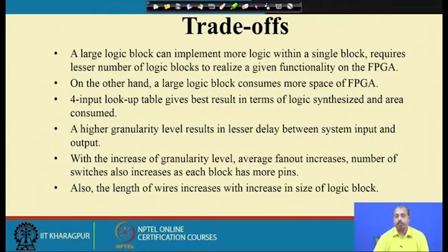On the other hand, a large logic block consumes more space on FPGA. As I said, for example, take this Xilinx XC4000 logic block that we have seen. This is quite powerful, no doubt. It has a large number of flip flops within it. So, say we have 1000 logic blocks, and each has 2 flip flops, so 2000 flip flops. Are we really going to use these 2000 flip flops in our design?